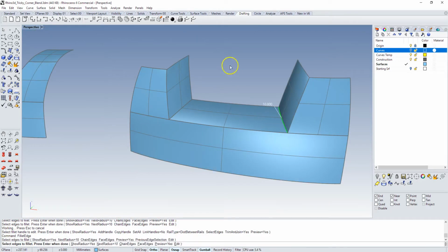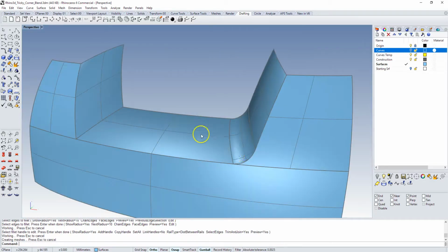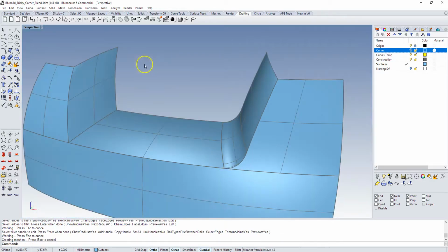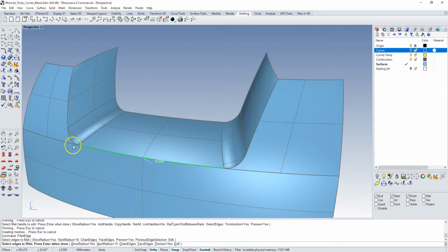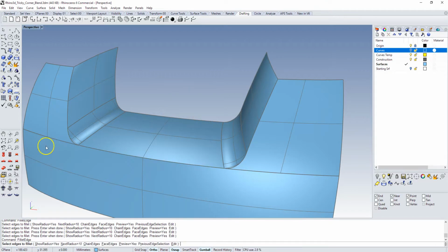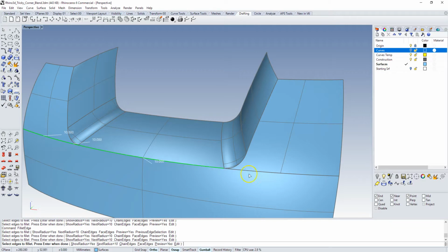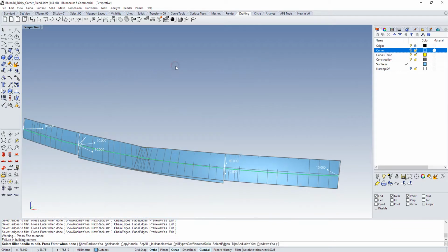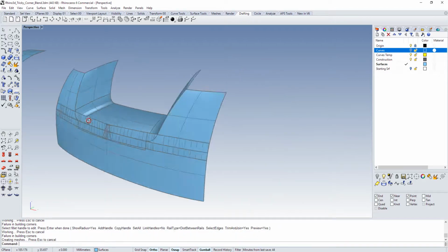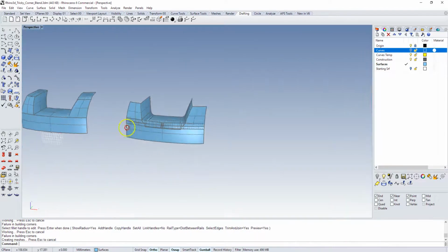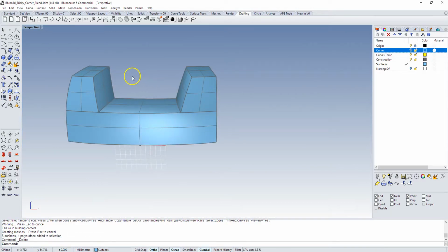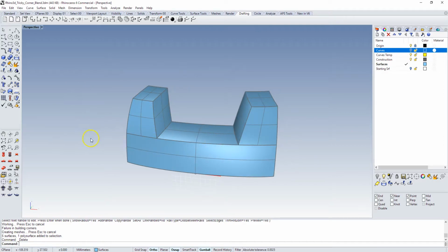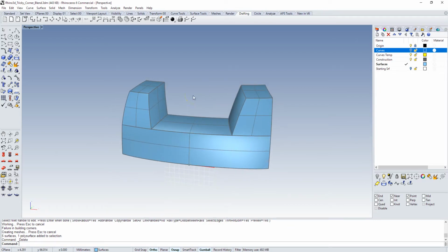If I try to do this instead, that worked, but you'll see that if I continue down that path, and I do this next, not that, now it just completely fails and I don't get a good result at all. So this is not the way to go about it. I find that in almost all instances, unless it's super easy, I consider these secondary surfaces, and I would blend these out by hand.